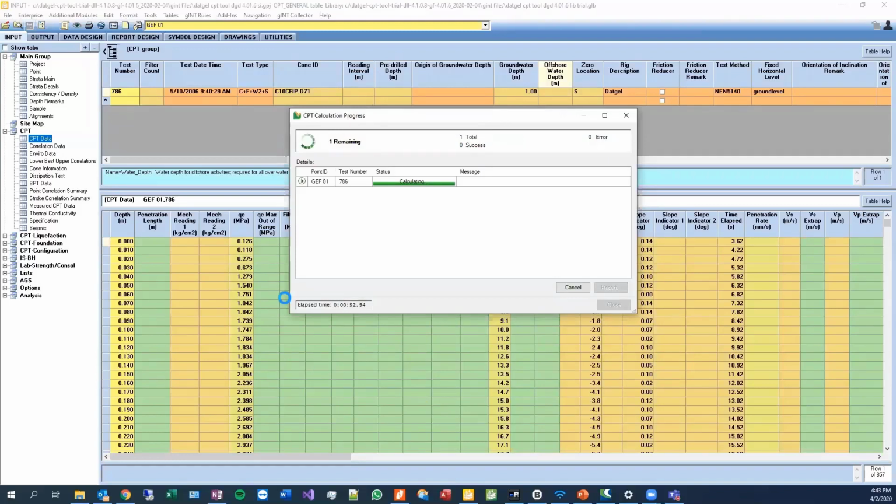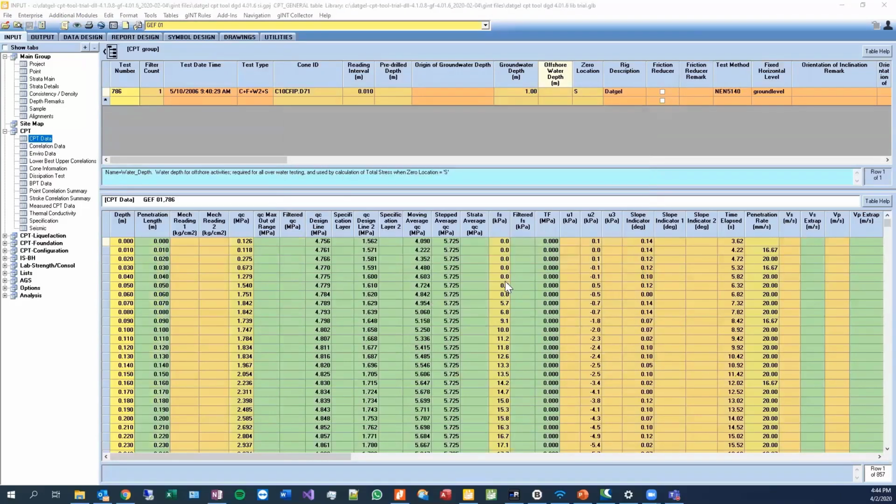Also, although I clicked change the value just then to prompt the calculation, I changed the value in this brown field. I could have changed one of the values in either brown, green, or brownish-green fields. That option can be turned off, so it doesn't always calculate every time you make a change. The other option is called the batch calculation, where you can prompt it to calculate all of your tests, or a bunch of tests, at a convenient time.